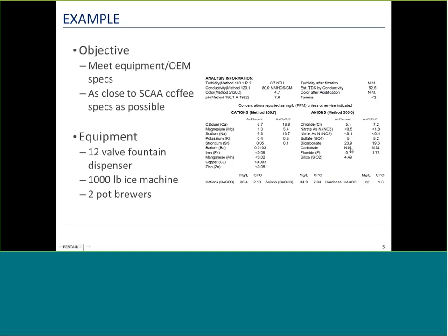equipment in the food service realm are constructed of 304 and 316 stainless steels, we need to look at what causes that corrosion. And principally, the most aggressive thing in the water we have is chloride. And this chart shows a tolerance chart for chloride compared to temperature for these two steels, which are the most common in the food service. And what's important here is if you notice that all these different applications, their temperatures are close to boiling, except for ice, which is a special case.